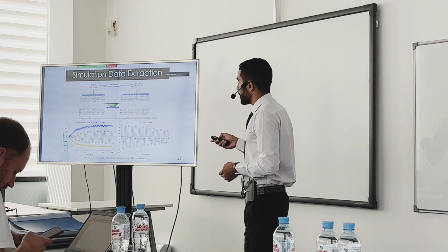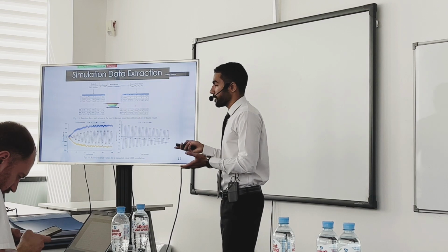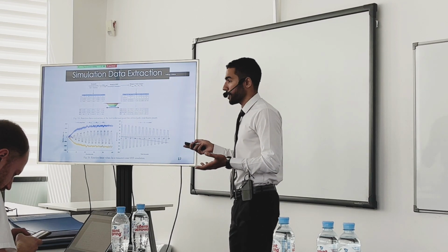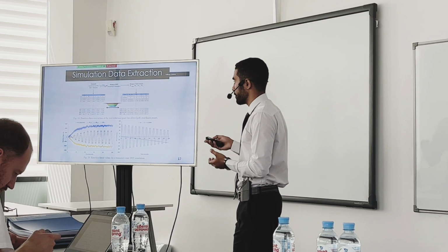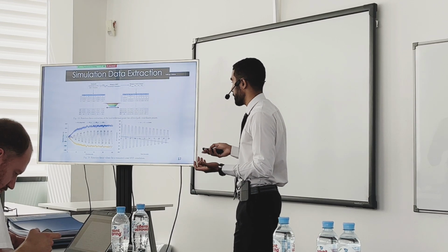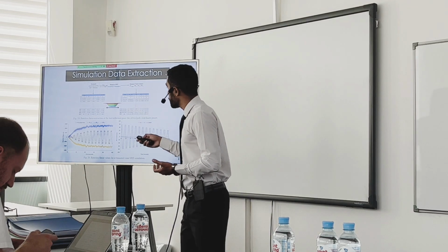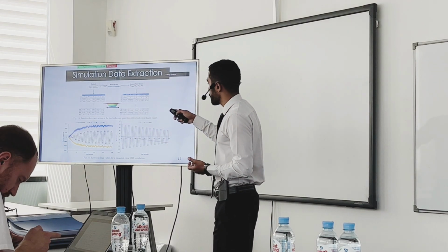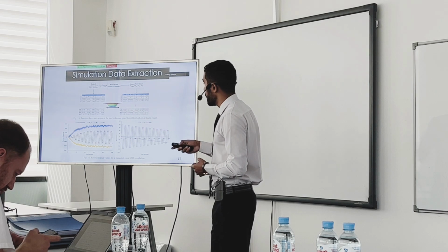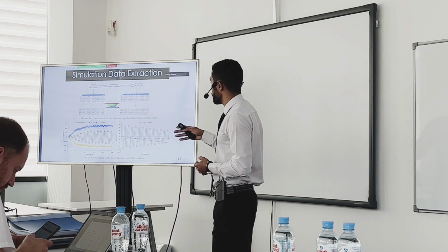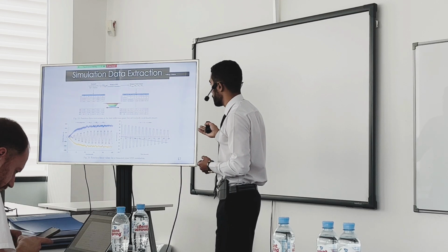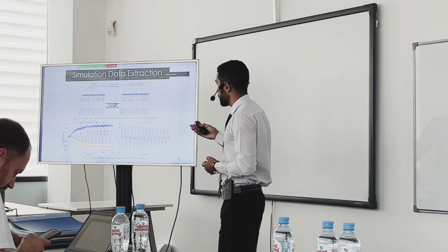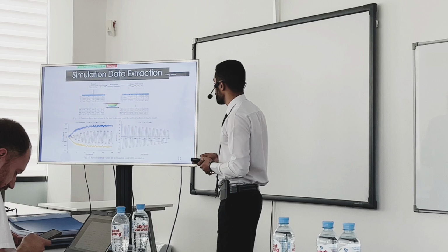And to implement the stiffness-based algorithm, I need some forces, the action forces of the sheet on the robot end effector. For this, you can see in the left part of Figure 19 this is my toolpath, and on the right side, this is the data generated from the numerical simulation tool, which is the magnitude of the forces.